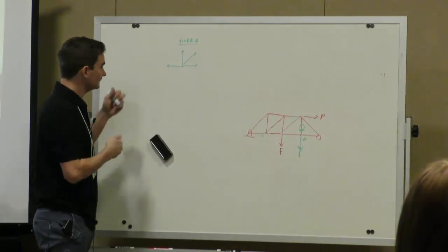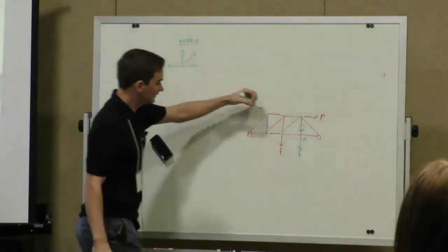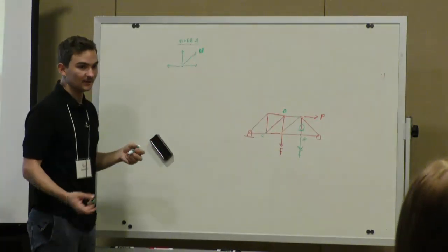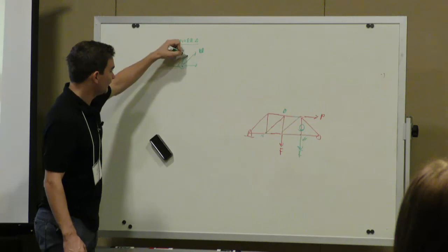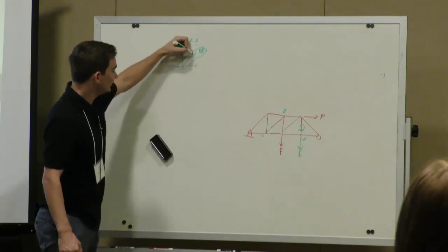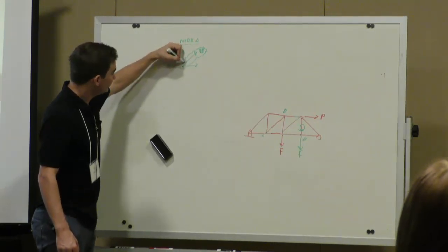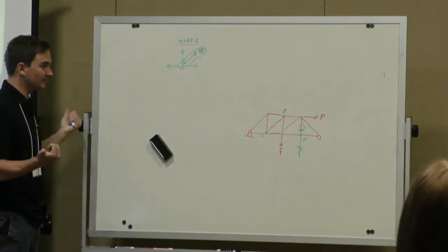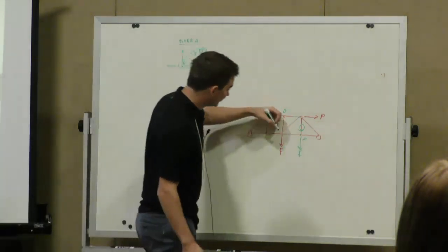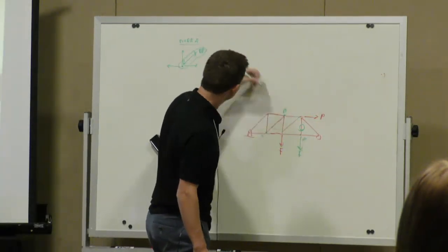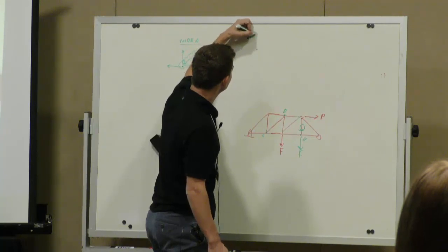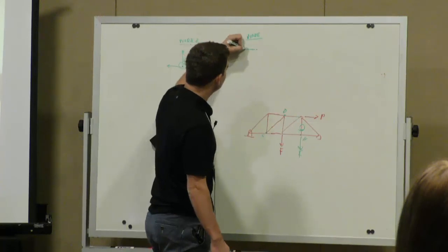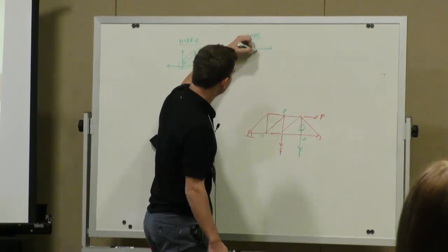So, for example, let's say this is AD, and we determined AD was in compression. The tip that Medeiros provides is you do your revision bubble, you cross it out, and you change the direction. So compression goes into the joint, tension pulls away from the joint. Now let's move over to node D, and let's say all these other ones are in tension. We haven't solved them yet.